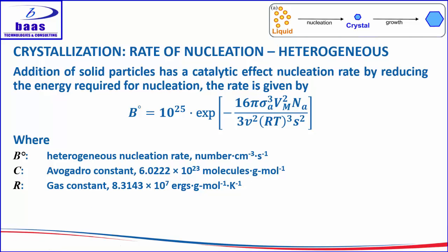The catalytic effect of solid particles on nucleation rate results in the reduction of energy required for nucleation. If you can remember, catalysis in chemical reaction results in reduced activation energy requirements. In that state, the rate of nucleation is now reduced and given by this expression.